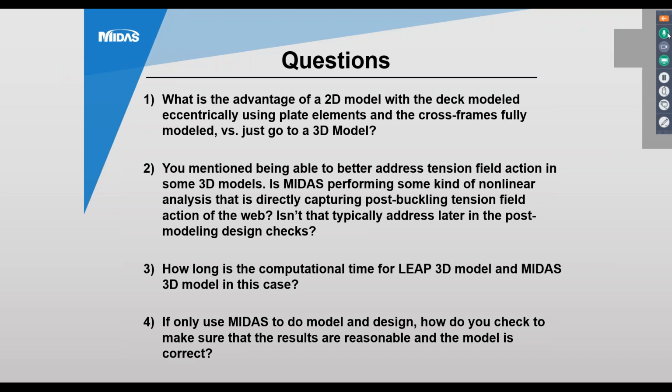And the LEAP Grillage was a little bit shorter time frame for runs than the Midas Grillage, depending on how you set it up. It's going to allow you in the LEAP Grillage to choose your step increment for the live load analysis, and that had a huge difference on the run time. So if you had 2 feet increments between where the live load could be placed versus if you had 6 inches between where they could be placed, you would see a vast difference in the runtime.